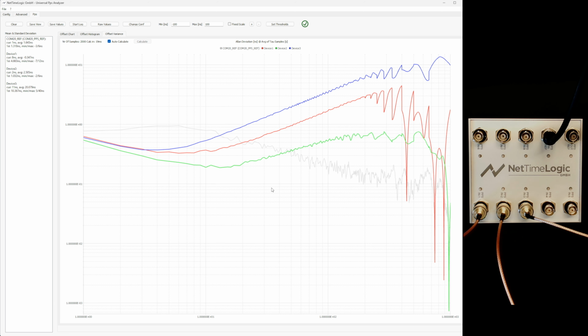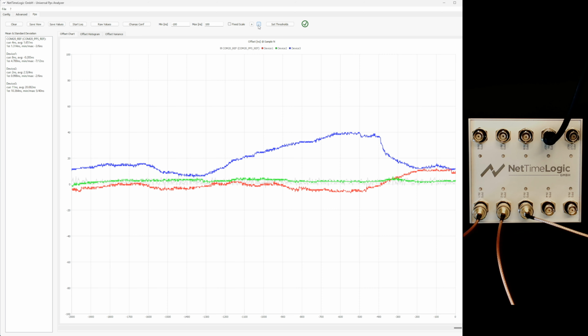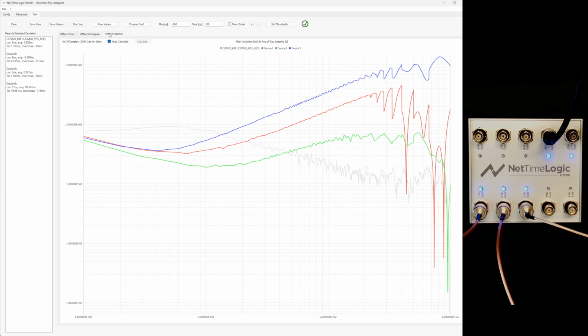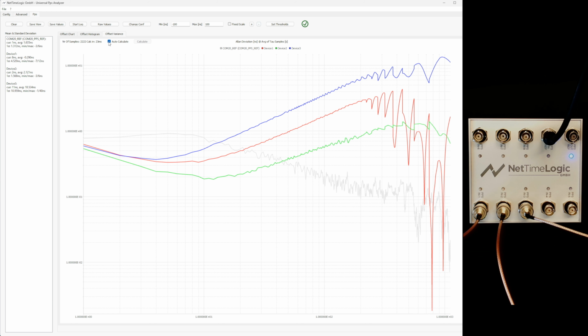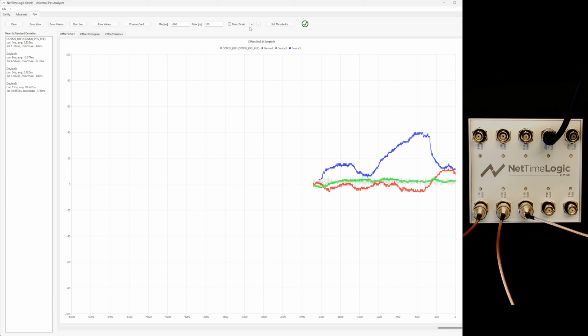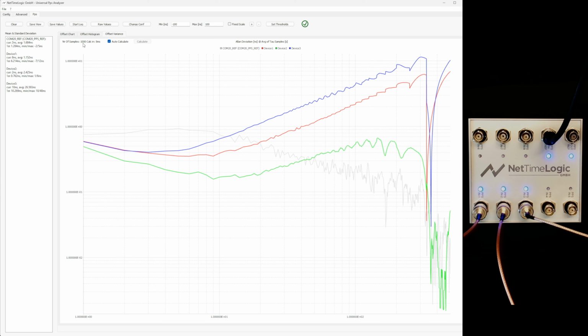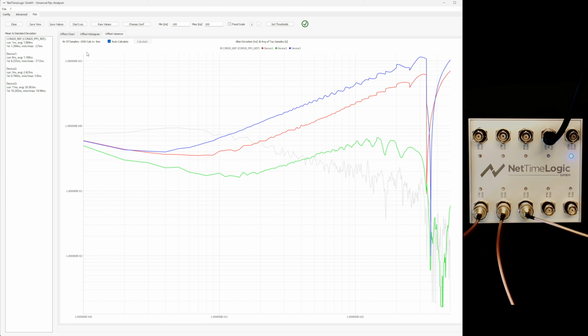Auto calculation attempts to calculate the variance every second, but it also depends on the calculation time for the number of samples, which is shown. The calculation is performed over the number of samples within your desired zoom level, so the current view is always used in the calculation. With a zoom level set to the last 1,000 samples, the Allan Deviation calculation is done over the same amount.